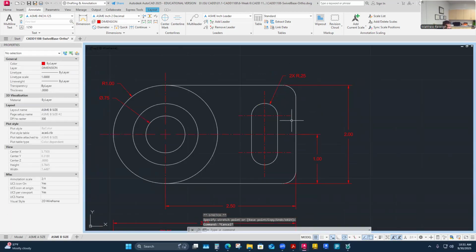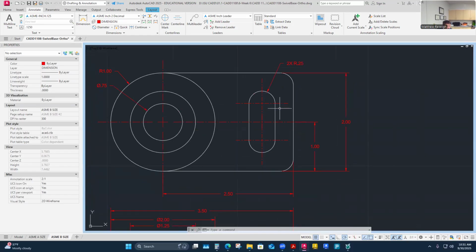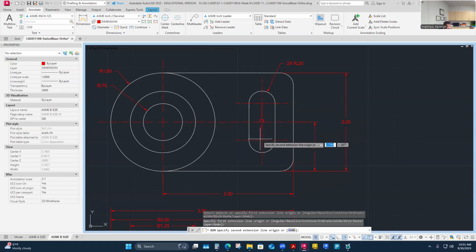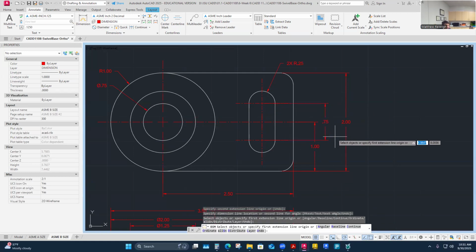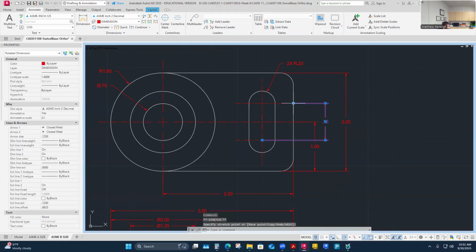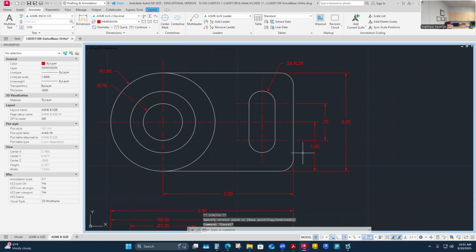That's a size, and then its size is also probably the distance between the two centers, which would be considered the size. So I definitely have this as a radius. But I think what I need to know for size is how far apart those radiuses are, right? So to me, this becomes a critical dimension from center to center. I know I'm crisscrossing dimensions. I'll deal with that later, but this is for sure a size dimension. This radius is associated with it in two places, and then that's the size.